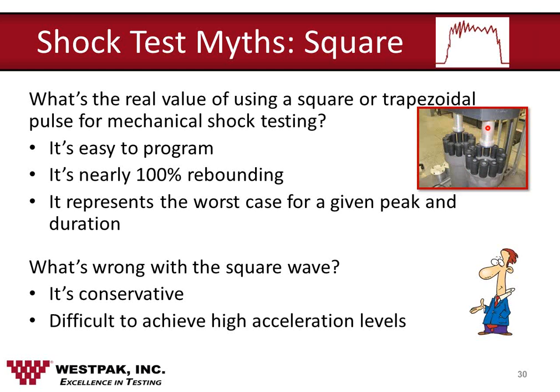These plungers are mounted on the bottom side of the shock machine, and they strike the pistons, and underneath them is nitrogen gas, which you can control very precisely. So you have everything you need. You control velocity change by the drop height of the shock table, and you control peak acceleration by the pressure in the cylinder. It's very easy to do.